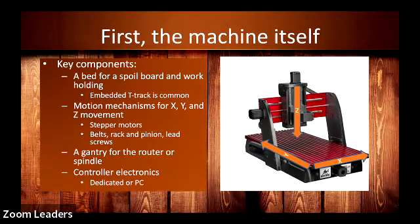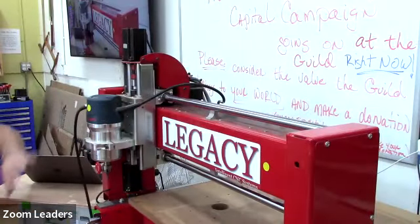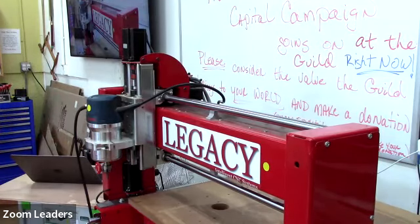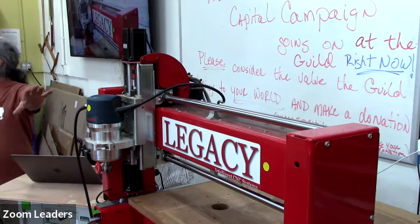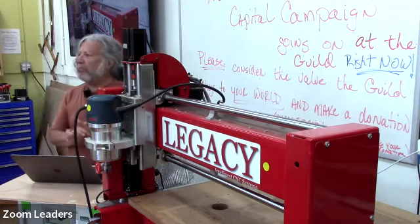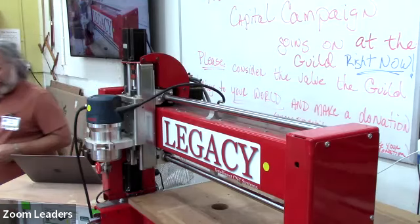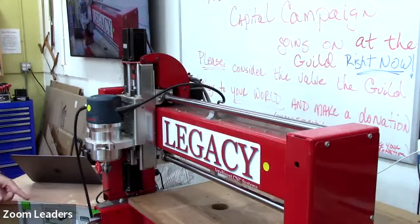The gantry is the thing that holds the cutting device. So this is the gantry all across here. This machine uses a router. It's a Bosch router. For higher end machines, we'll talk about spindles, liquid cooled, and for production work. But for low to mid-range machines, a router like this, a couple of horsepower router, is the typical thing running it. And then you need some electronics to control the gizmo. In this case, we've got a small PC that's running the machine control software sitting underneath it.